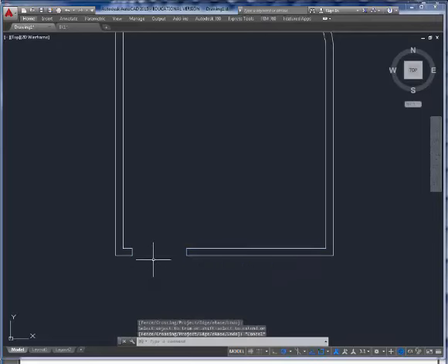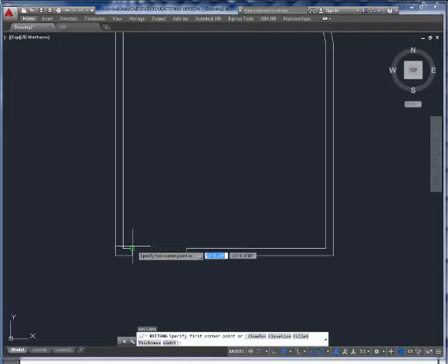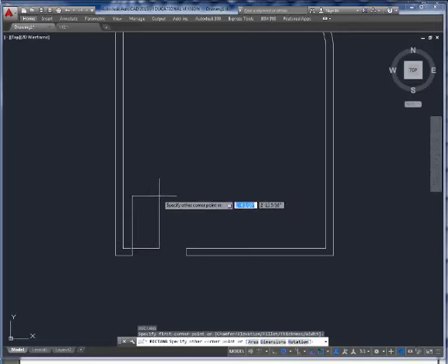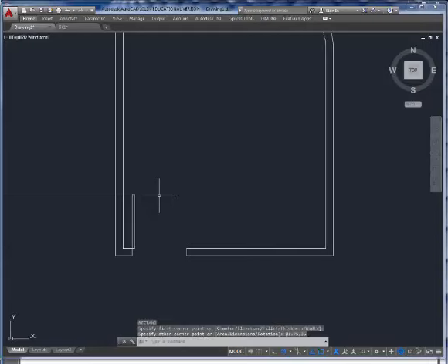I'm going to draw the symbol for the opening of the door. Here is rectangle. I'm going to locate the hinge position of the door, and I'm going to say at. The standard thickness of a door, we are going to use 1 3/4. You can see that AutoCAD also takes decimals. We're going to say 1.75, comma, instead of 3 feet, I'm going to say 36 inches. Inches is the default. I don't have to worry about telling the feet and the inches if I can just give the inches. I'm going to say A for arc.